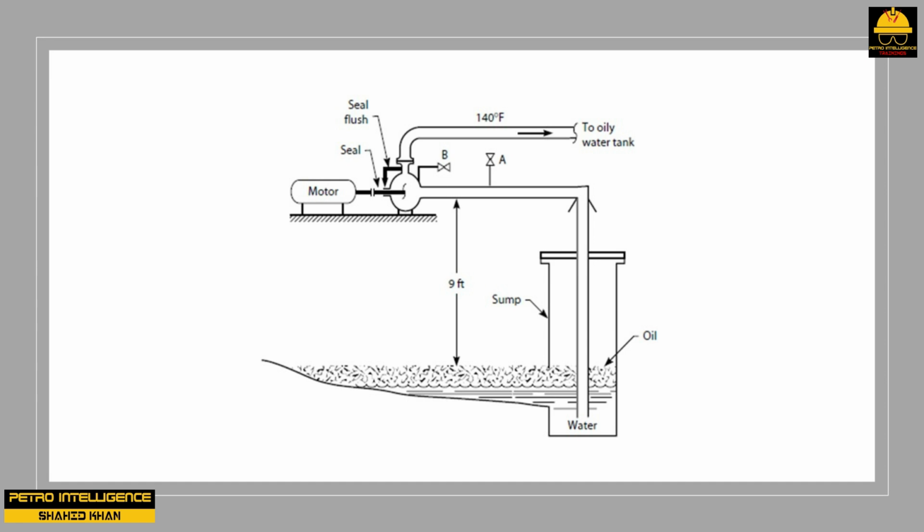In the picture, this is done by connecting a water hose to valve A and opening valve B. Air is pushed out of the pump case by the pressure of water in the hose. When the pump is in operation, the suction pressure of the pump is -4 psig. This negative pressure creates a potential problem. Air may be drawn into the suction of the pump through leaks in the suction line.